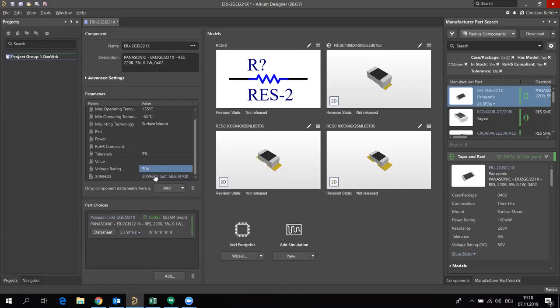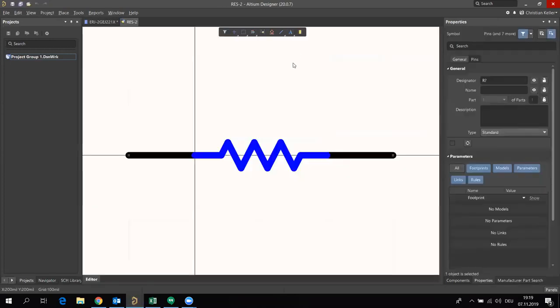I can find the data sheet here as well. So it's downloading this too, saving it to Concord Pro. It gives me, of course, the manufacturer and the manufacturer part number, and tells me where I could get this component from, and if there is some stock. And quite some components are available here. And it's downloading as well a schematic symbol and footprints following IPC norm, three different kinds. But all this data can be changed by you if you want to.